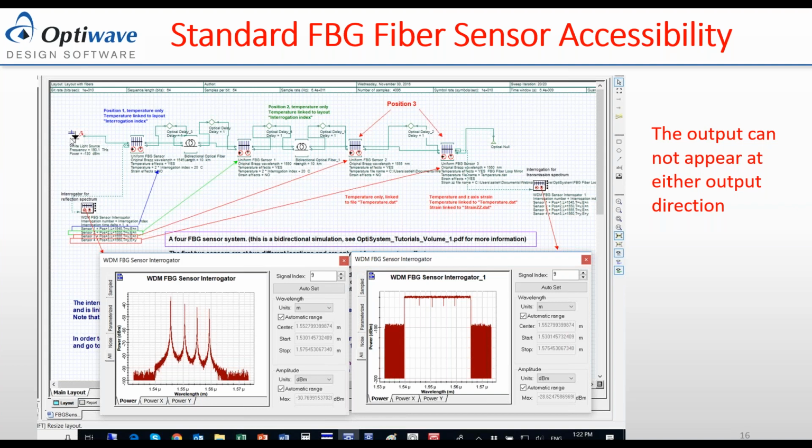Now, if you have a laser diode in here, and this laser diode is set at 1550, and the grating is set at 1560 nanometers, then basically the light is going to be transmitted through the grating. All the light is going to transmit, and no light is going to be reflected here, and you will not be able to measure anything. So that's the advantage of using an LED in this kind of application, unless you have, for example, a mechanism to track the laser, which is very, very difficult. It's recommended to use an ASE source and/or LED for this application.